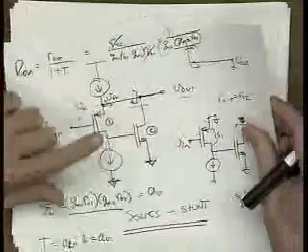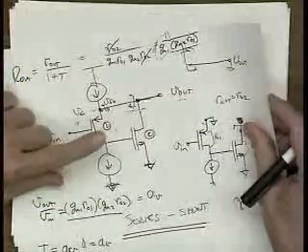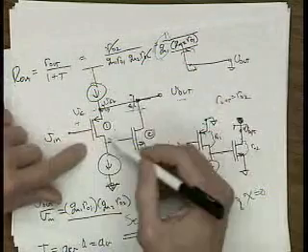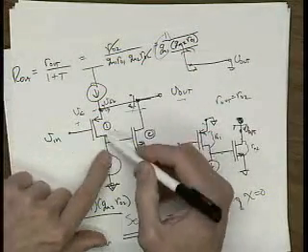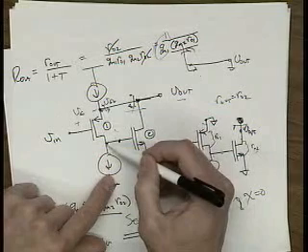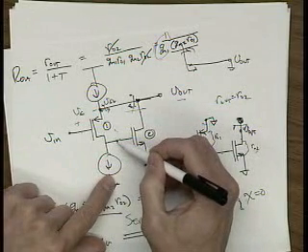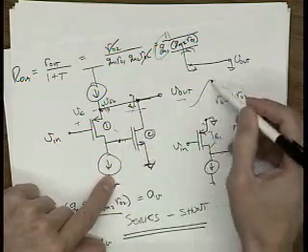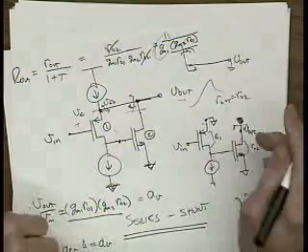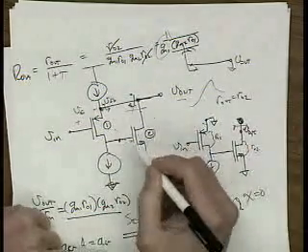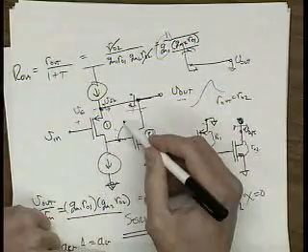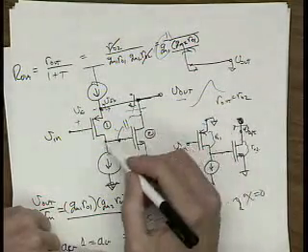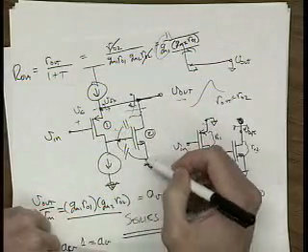That's why you saw this circuit had some interesting poles going on when you use this thing, right? Because there's a high gain stage right at this point, here's a high output impedance. There's a lot of gain to this point, okay? So you've got a point here which is a fairly high impedance node. You guys started seeing peaking in the response from using this circuit in your last project, right? Because right in here, look at this is R0. It's not a lot of Miller multiplication because the gain's only 1, but you're still going to see R0 times this capacitance on this node right here. Right?